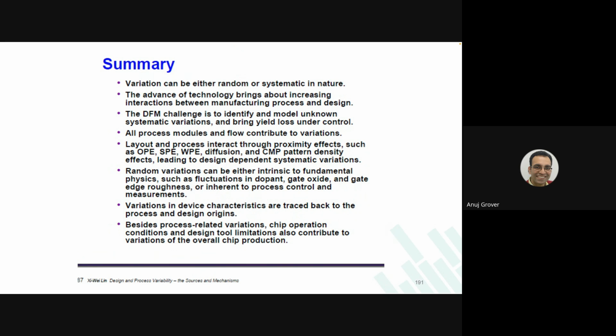So people started to look at every place where they were leaving margins. And they said, oh, I don't want to give OCVs. I don't want to give OCVs for variations. You characterize the memory with statistical timings. So this need started to come at that time. And today SSTA is what is typically done. We don't want to leave margins for hold and access time both. You characterize per bit so that we are more accurate. So there is a much stronger focus on accuracy at the characterization level so that at chip level you can reduce the OCVs and somehow gain performance.